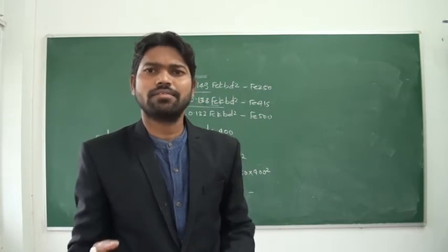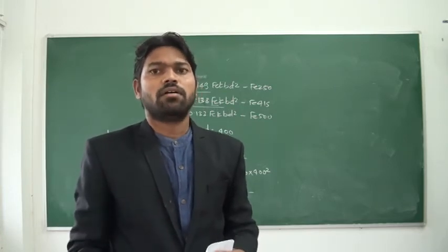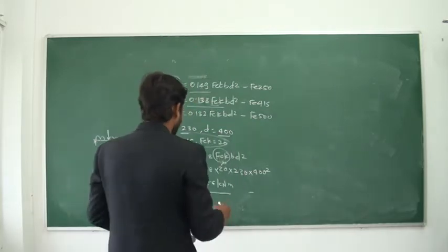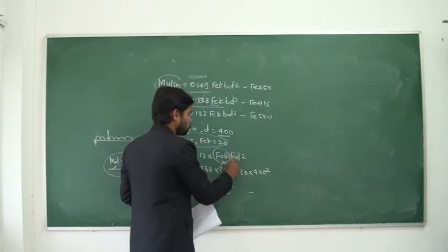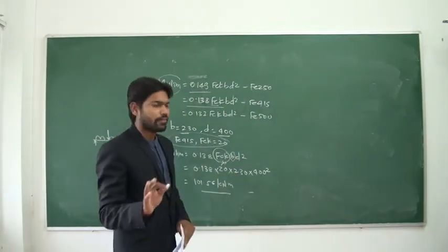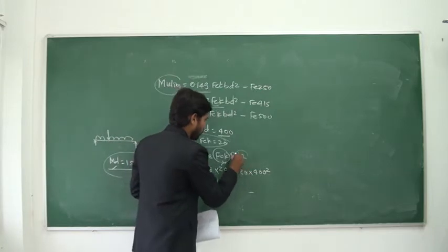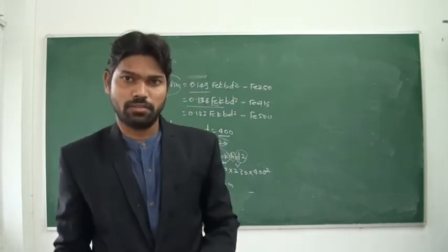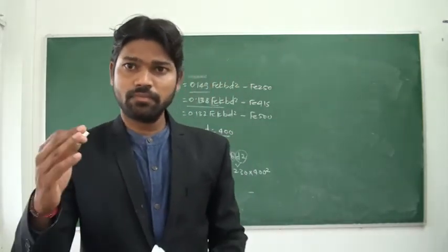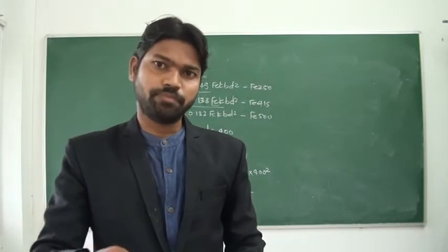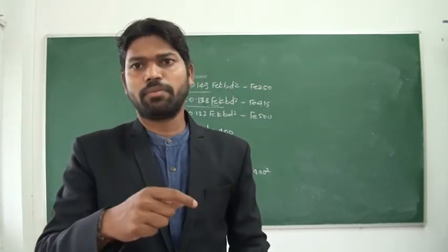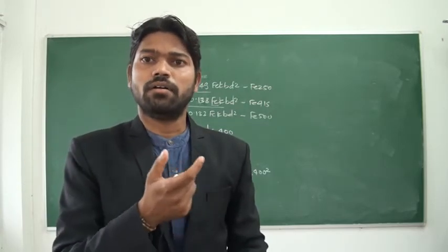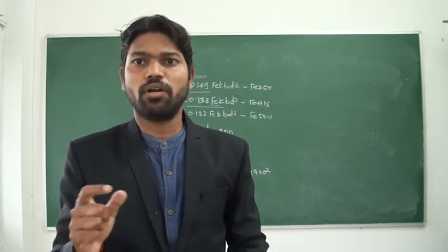In some exceptional cases, the width of beam you can change. So this option can be used, but in rare cases, not frequently. Then only one option remains, that is depth of beam. So depth of beam can be increased, and if you see the depth of beam in one particular building, it is different for different locations. It will not be like all the beams of a building carrying the same depth. It will not be possible.